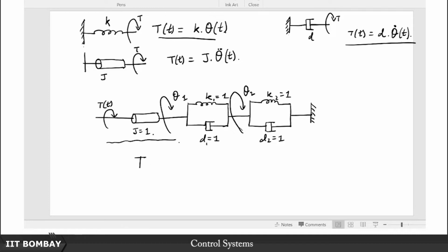So the applied torque here, if you look at this portion, is balanced by what? Of course, there is this J, so it is J times s squared. Again, I am writing directly in the Laplace domain, so if you translate this to its equivalent, then this is s squared J theta of s. This is the transform domain equation, so we are going to directly write in the transform domain here itself. So you apply this torque here, it is balanced by a pseudo rotation, like we had a pseudo force. If you want to bring this to static equilibrium, it has got to be balanced by this J s squared.